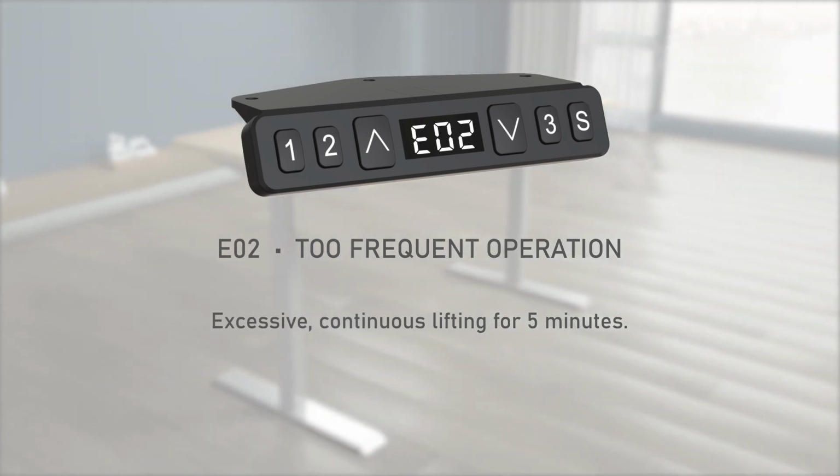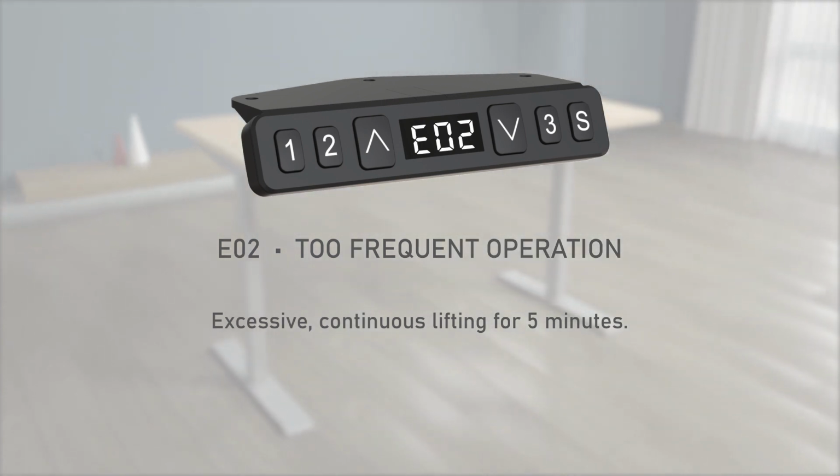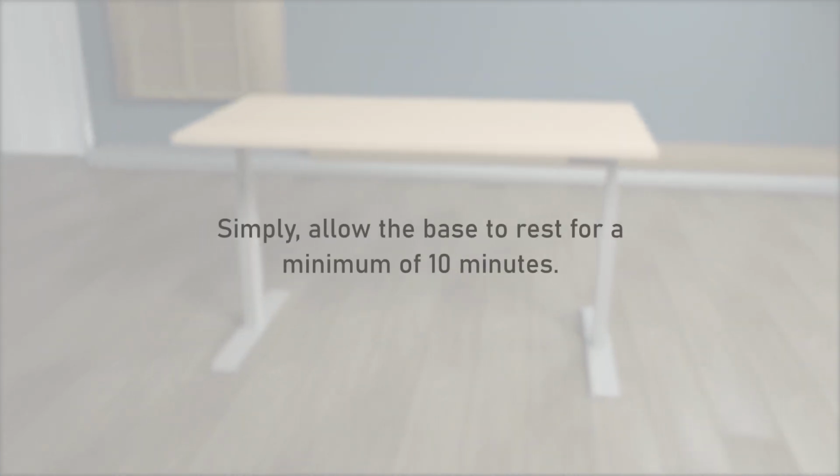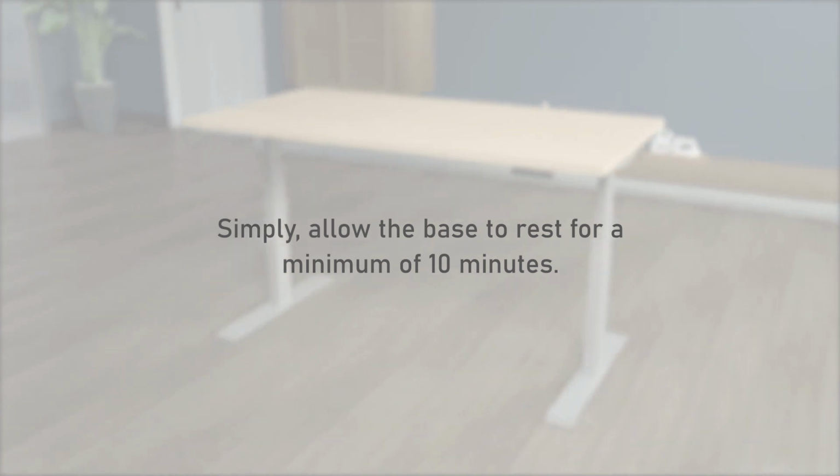E02, too frequent operation. Excessive, continuous lifting for 5 minutes. Simply allow the base to rest for a minimum of 10 minutes.